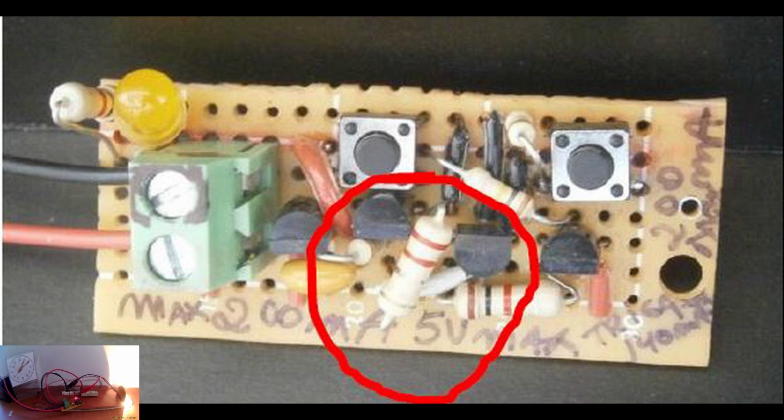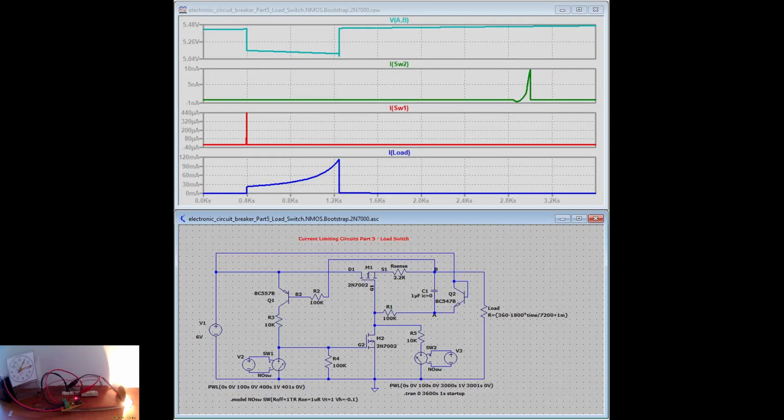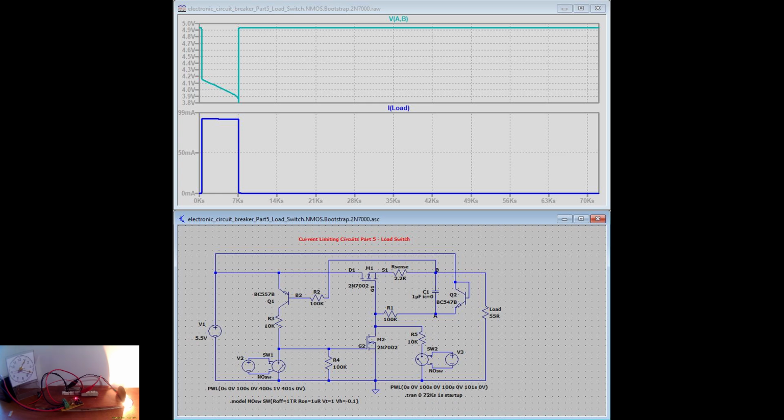With the inclusion of a 2.2 ohms R-sense resistor, the circuit limited the current to 140 mA. The limit showing in the picture is for a 2N7002 MOSFET and not the 2N7000 used. This resulted in the circuit staying on no more than 2 hours while driving a 100 mA current. The R-sense voltage drop has to be taken into consideration now, as the voltage drop in the R-sense resistor added to the drain to source voltage shuts down the circuit earlier.